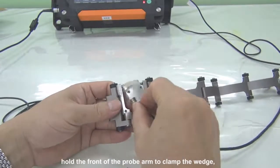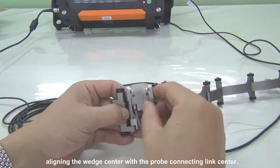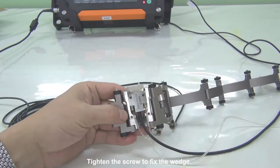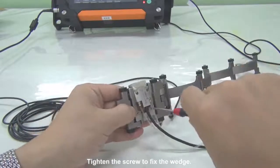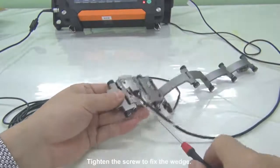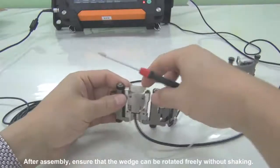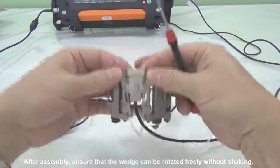Hold the front of the probe arm to clamp the wedge. Adjust the wedge position, aligning the wedge center with the probe connecting link center. Tighten the screw to fix the wedge. After assembly, ensure that the wedge can be rotated freely without shaking.